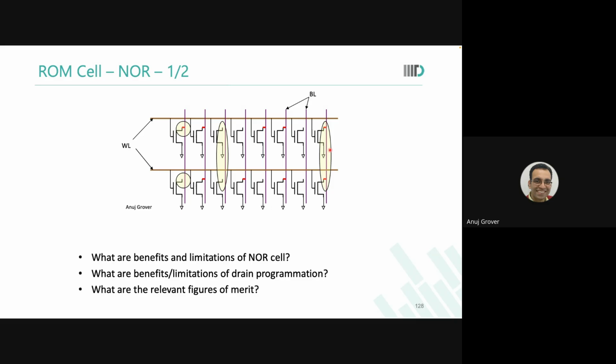Yes, bitlines which have lower capacitance will consume lower power, probably. Okay, but it doesn't really help me because I have to design my cell timing for the worst case cell only. So even if that bitline was lesser capacitance, it will discharge more now, because my word line is going to be on for the required duration.